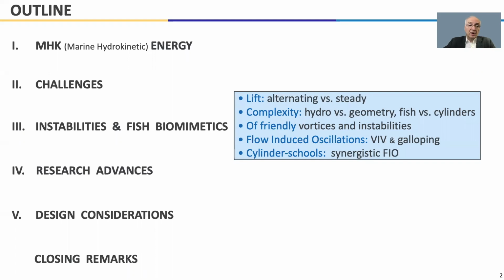We have developed a concept that we introduced back in 2006 at the OMAE conference in Hamburg. And there have been a lot of universities and laboratories around the world that have done an excellent research job. There are more than 1,000 papers and publications on the issue of generating hydrokinetic energy using vortex-induced vibrations and galloping. As you know, VIV and galloping are destructive phenomena that we're trying to suppress in offshore engineering. In this case, we're trying to enhance them and control them.